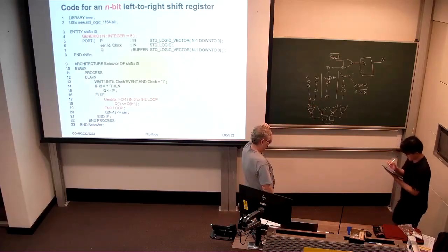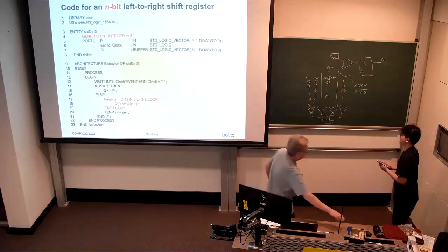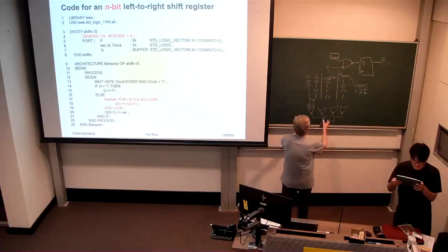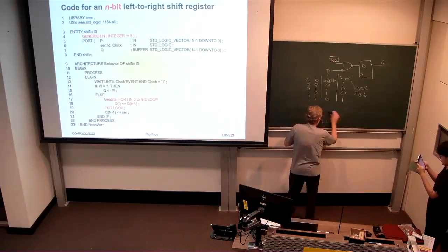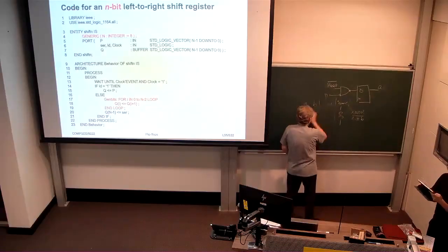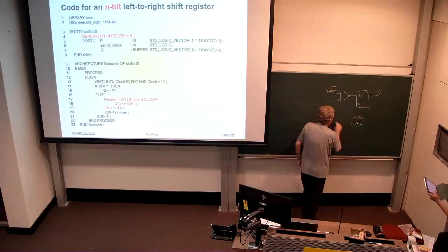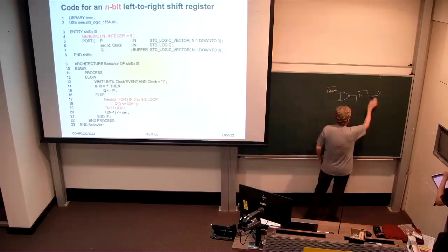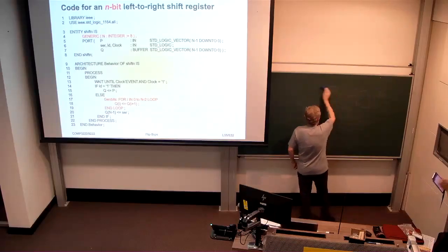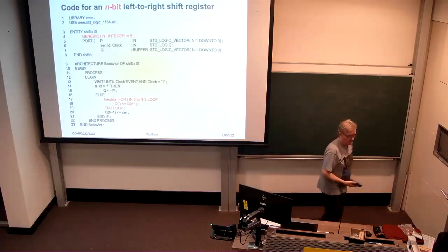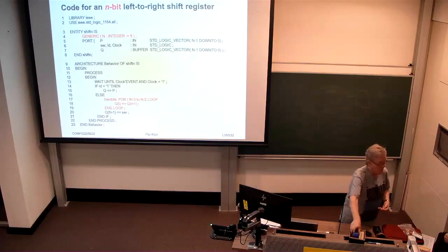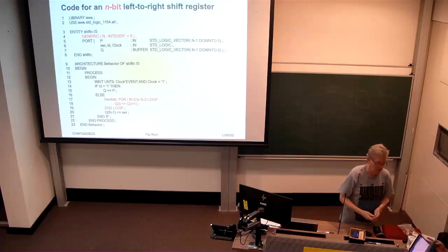Okay. Does that make sense? Yep. Bit simpler than the full adders. You don't need the full adders. Yeah, I'm sure that will do it as well. If you had to do it, it's perfectly acceptable to subtract the one from the other and check that all bits are 0.